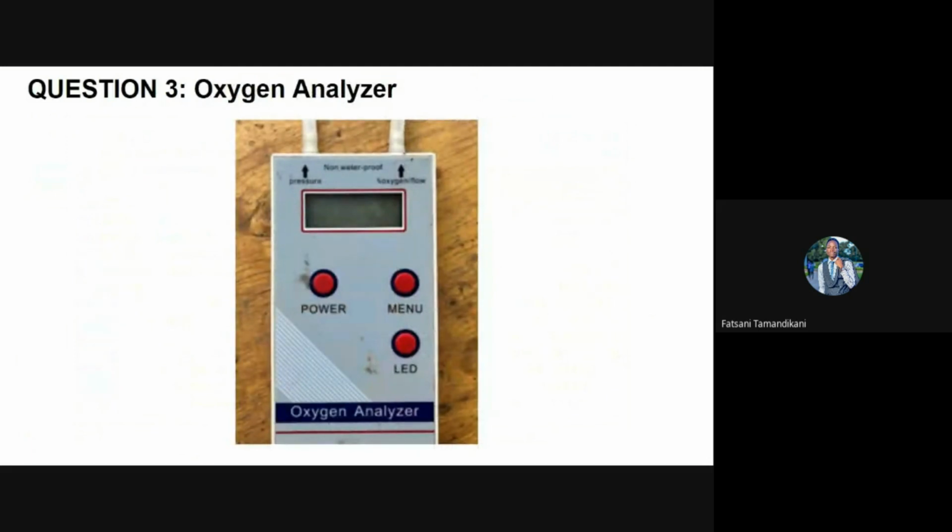All right, next I'm going to look at filters. Oxygen concentrator filters protect the concentrator and patients from dust and other inhalable particles and risk of infection. The concentrator has different filters placed in different locations, and these include the gross particle filters, intake filters, and bacteria filters. These usually come with the concentrator, but it's good to have spares because it is not advisable to use concentrators without filters. Filters are regularly replaced during maintenance.